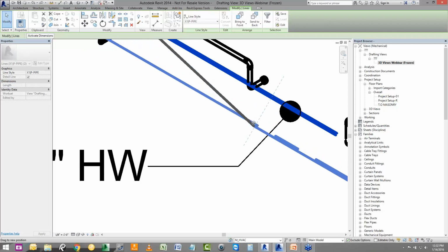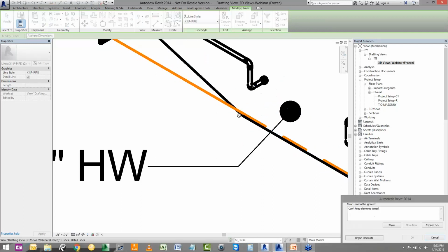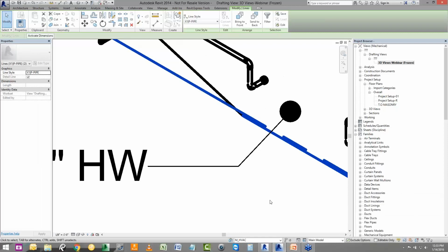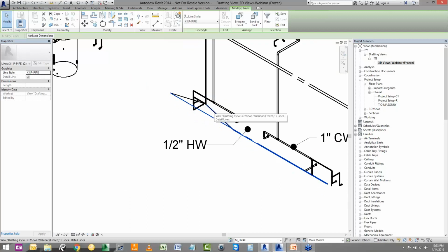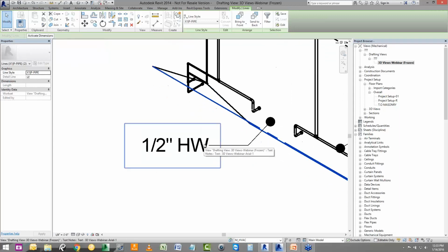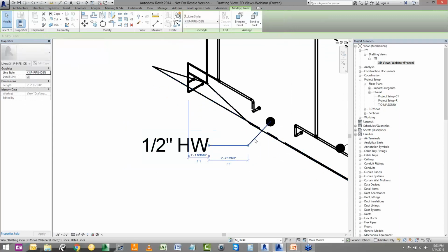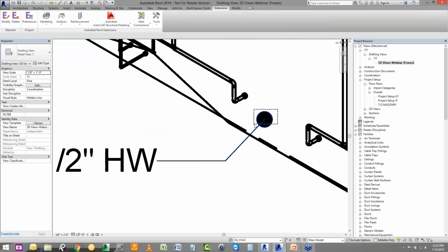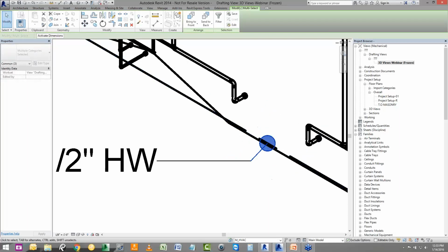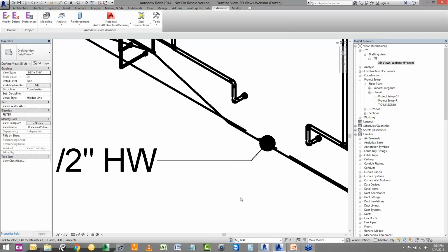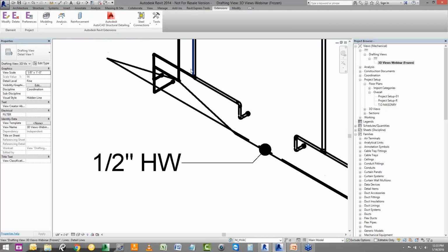Obviously you have to pay attention to what you're doing here because Revit understands connectivity, so it understands this line connection. You may have to unjoin some elements depending upon how far apart you want to place them, but this gives you the ability to stretch out an isometric without having to affect the model design. Also here we can change any of this because this is now line work as well, so I can do things like highlight here and use my move command to move this entire thing here on back onto that line. Okay, Revit still understands some basic connectivity with this line work, as you can see here and as you can see right here.